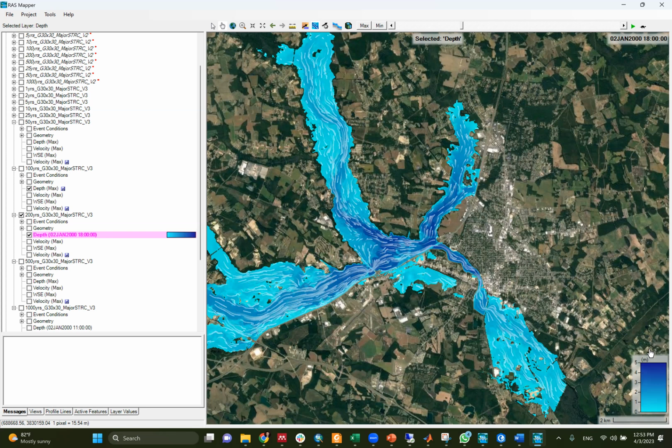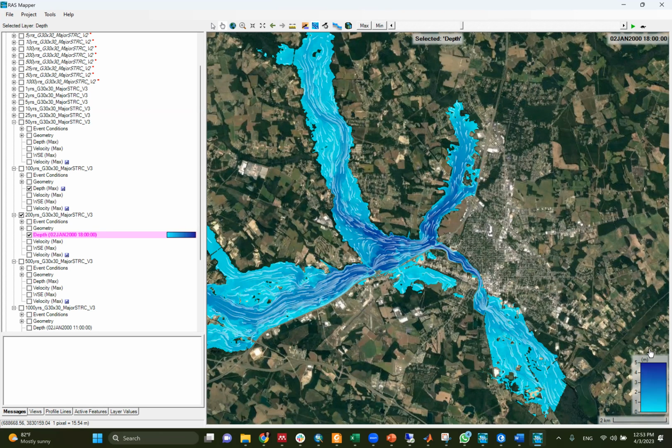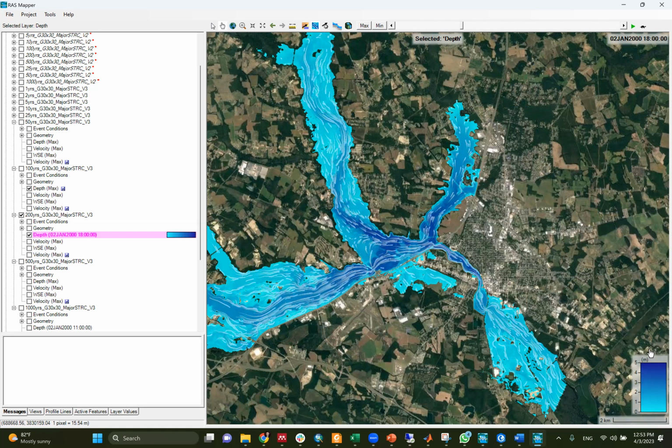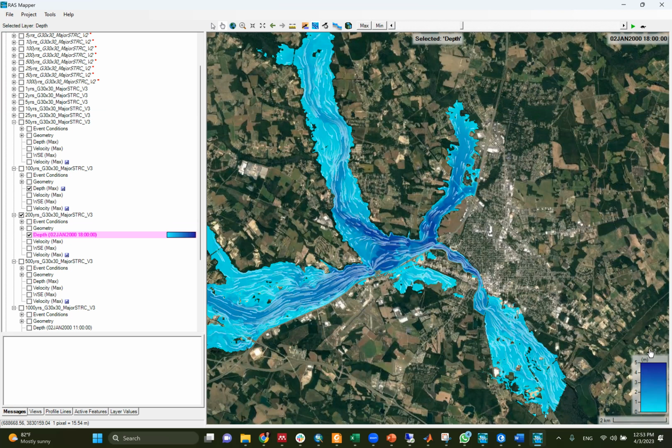So if we have a barrier of 1 meter, you are basically making an if statement. You are not changing anything. You will make an if statement. If the flood depth is less than the barrier height, the loss is 0. But if the flood depth is more than the barrier height, you will basically use this flood depth, because the barrier will be useless, like there's no barrier, and then we will use the fragility function, right?